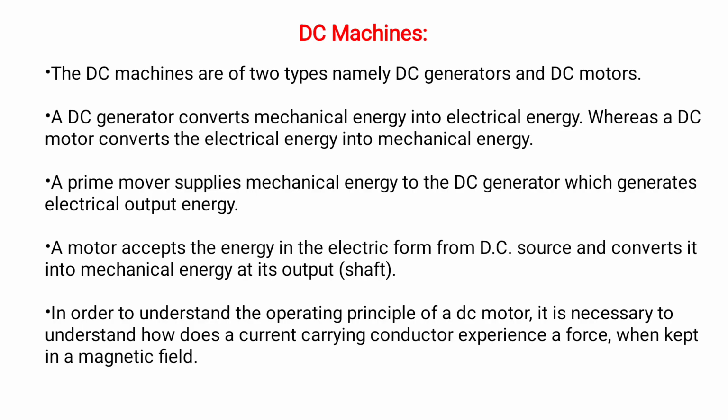Now what is Faraday's electromagnetic induction? Whenever we put a conductor in a magnetic field, either by the rotation of the magnetic field or the rotation of the conductor, an EMF is induced in that conductor. This is Faraday's first law of electromagnetic induction. The motor principle is the Lorentz law. So what is the Lorentz law? Whenever a current carrying conductor is placed in a magnetic field, it experiences a mechanical force. That is the Lorentz law.